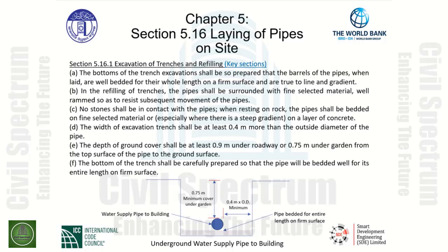Item F, finally, the bottom of the trench shall be carefully prepared so that the pipe will be bedded well for its entire length on a firm surface. As indicated in the graphic below, we have a water supply pipe running to a building. Below the pipe, we have bedding for the entire length on a firm surface. This will be fine graded material, selected material, that is utilized to support the pipe.